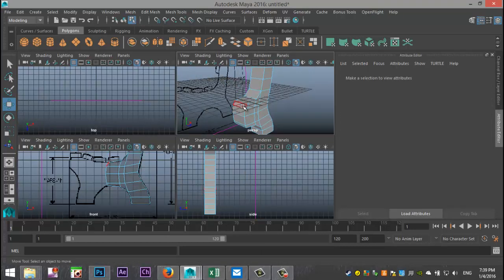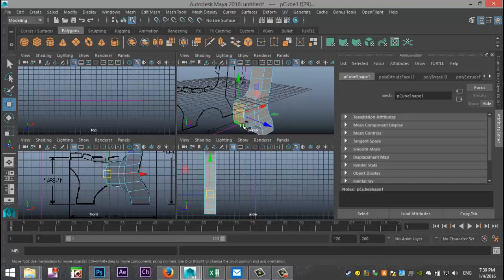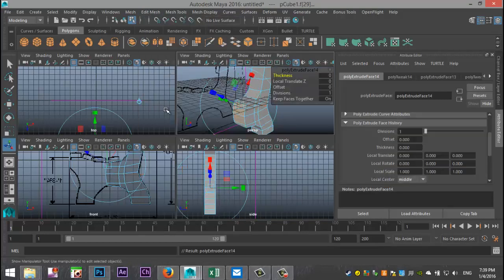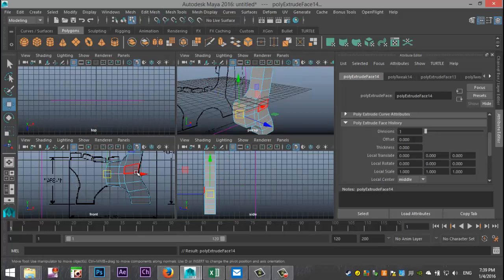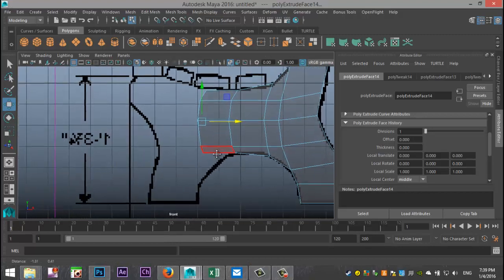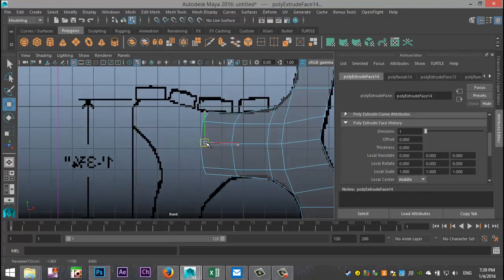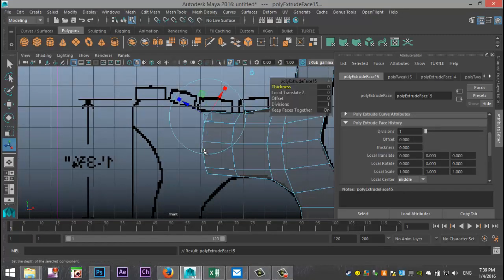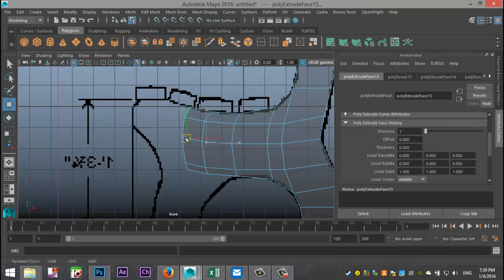Right click face, edit mesh and extrude again. W to pull out. And we'll just focus on the top for now. G to repeat, W to pull out, GW, and GW until we're about here. Okay. And then we're going to take these top three here.